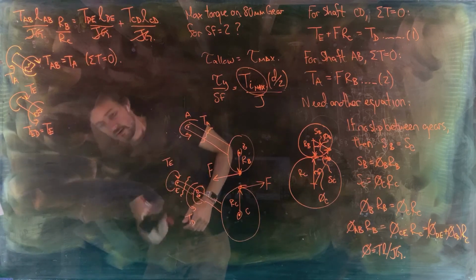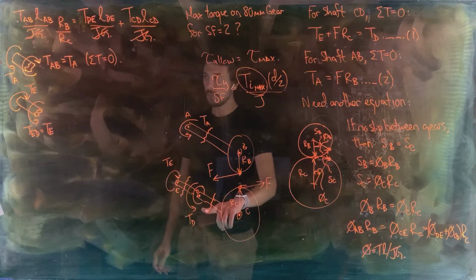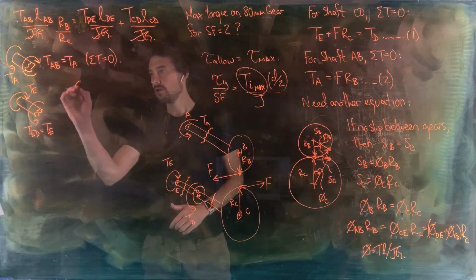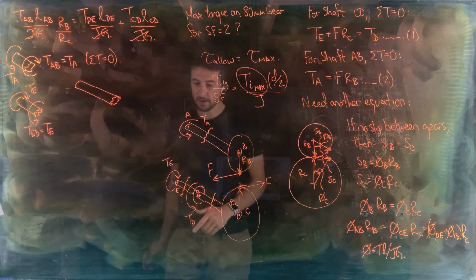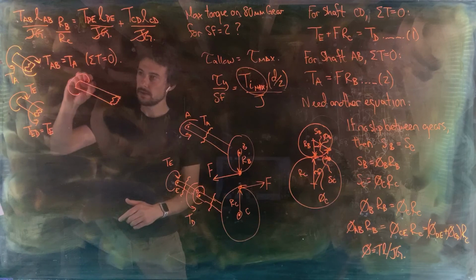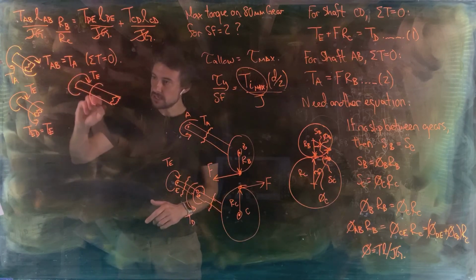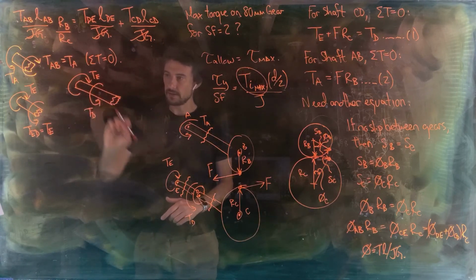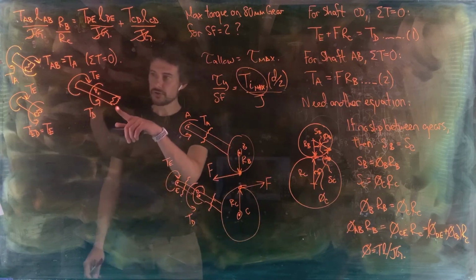And then one final one, a section cut through there. And again, I'm going to draw the left-hand portion of this. So we've got a free body diagram now that looks like this, where this is TE. We've also got TD applied. And I'm not drawing the gear there, but the gear is there. So this point D here. And then I've got the internal torque, TCD.